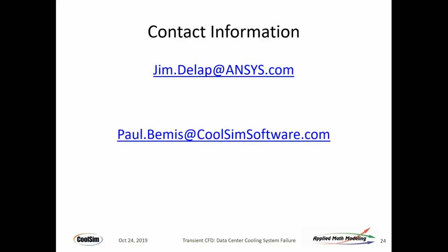Is the IT fan flow simulated during failure? You can simulate the IT fan during failure, yes. You can do it in a variety of ways, but we aren't right now ramping those fans down as a function of time because we're just assuming they're going to zero fairly quickly, and they do go to zero fairly quickly. Studying the effect of the thermal condition during the ramp of the fan from full speed to zero is of some interest, but in the general case, it's not going to matter all that much with respect to time.